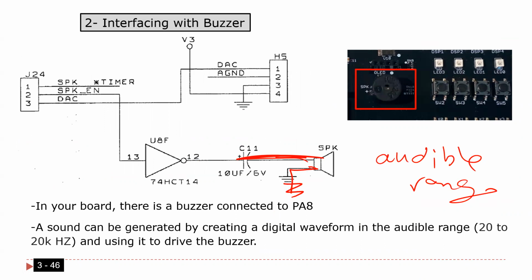Also, what I said, the buzzer is used to generate sound, to hear some sound. I told you all what you have to do, just generate a square wave. That's it. And similar to what we did before, for the pin you are going to use, you have to configure this pin as output. That's exactly what we are going to do right now.